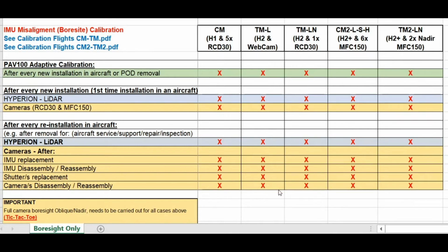So basically this is what we know. I'm looking for planar surfaces that are tilted in both directions: a large building, warehouse, hangar. The ground level should be well defined, avoiding any vegetation. It is preferred if the area already has a control point, but that is not a must. Then here are the general parameters. We fly the Lidar at 2,000 meters.